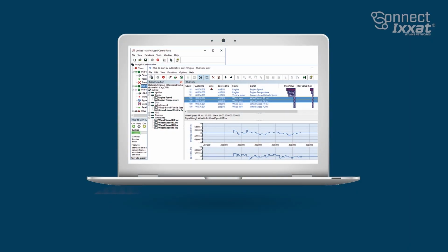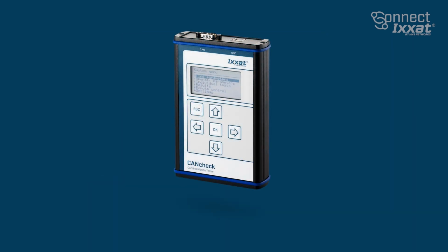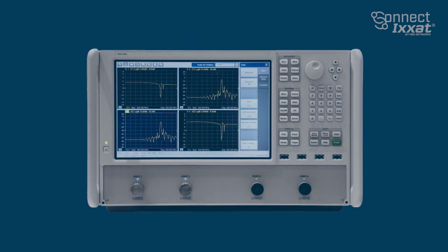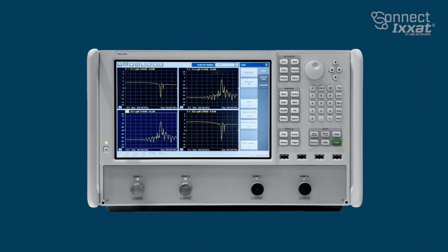It seems having the right tools for testing and diagnosis is essential. Could you remind us in particular what kind of tools are used for this? Tools like the CAN Analyzer V3 are great for tracing down errors and doing a frame analysis. The CAN check is used for wiring checks and an assessment of the signal levels. And an oscilloscope is invaluable when having a detailed look at the signal levels, flanks, reflections, and disturbances.